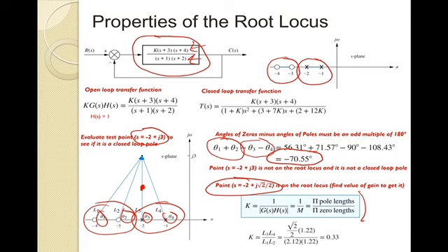And what we'll see here from this criteria is the value of k is going to be the product of the lengths of the poles. So poles right here in x's, that would be L3 and L4. We can find those two lengths. Then we divide that by the product of the zero lengths. That would be our L1 and L2 terms. So I've listed here L1 through 4 as shown. I'll, again, leave it to you based on the previous module to come up with those.